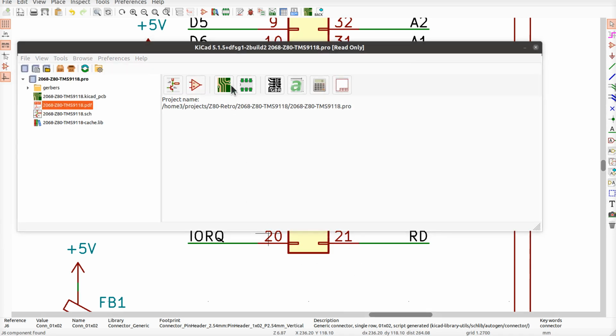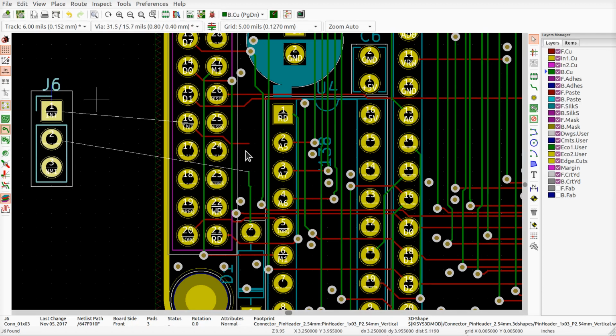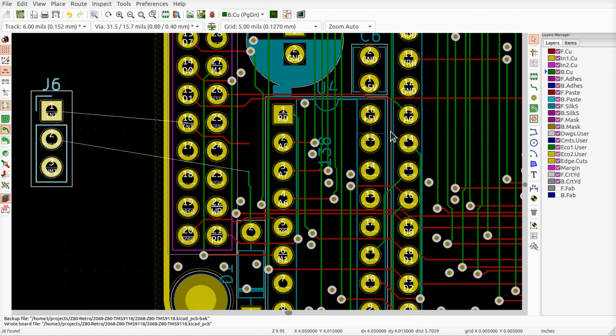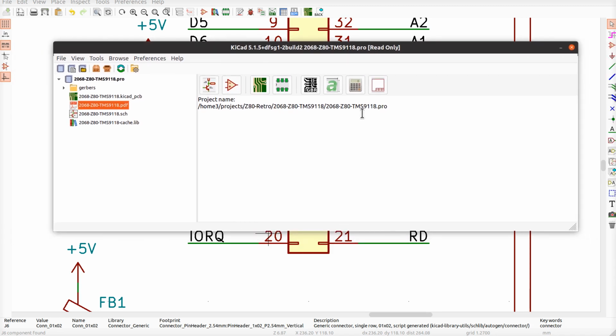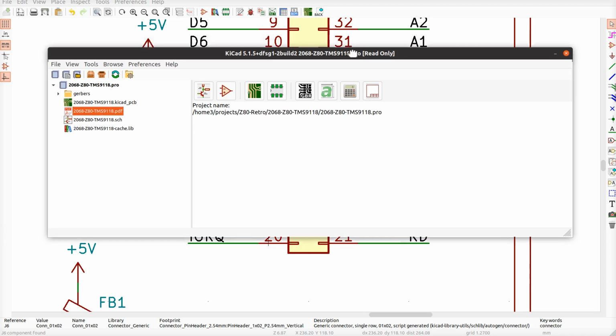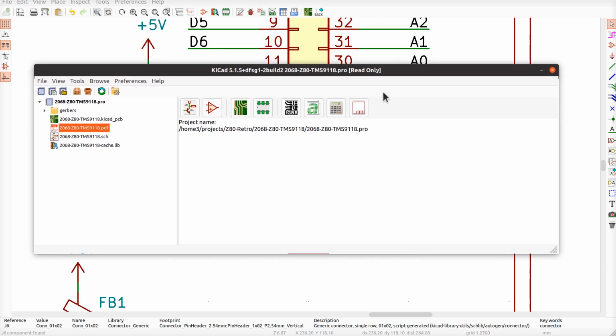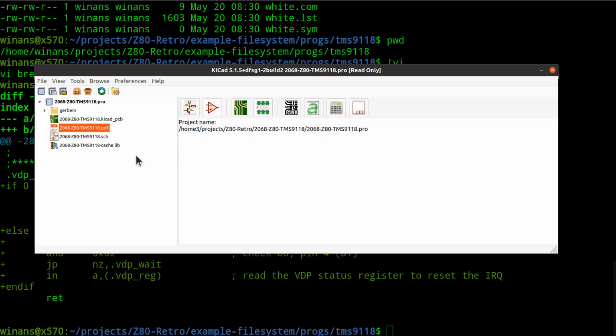So I'm going to press Control S to save this. I'm going to go back to the circuit board and Control S to save that. Control W, or what is it, Control Q in this window to close that one. Now be careful with Control Q, because somebody in their brilliant genius changed the meaning of Control Q by default in newer versions of KiCad, and it'll close the entire thing out and blow away all your windows and everything else. Not that you can't just start up KiCad again, but they've changed that, just FYI.